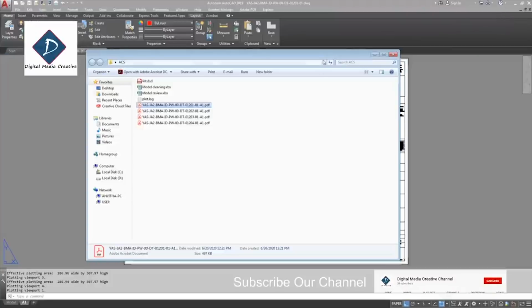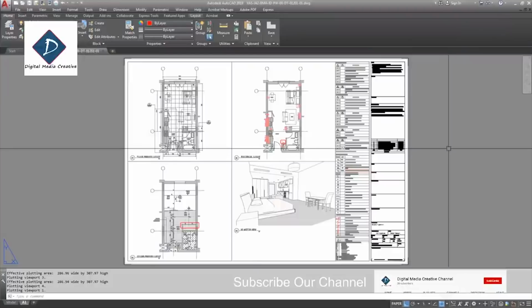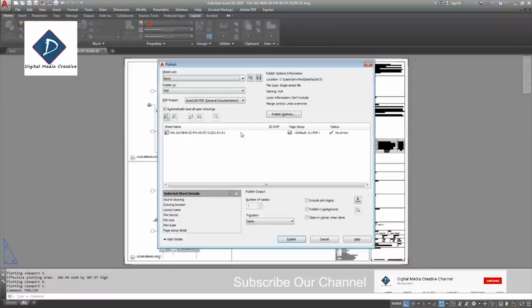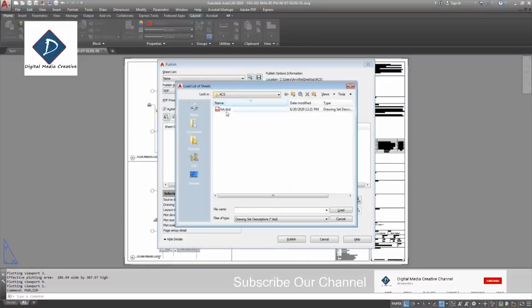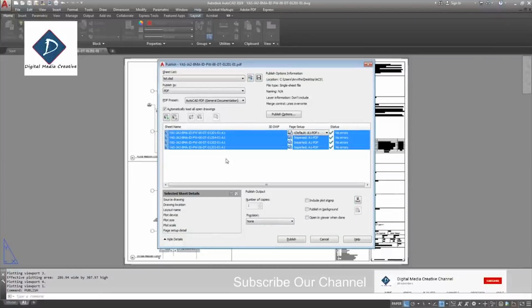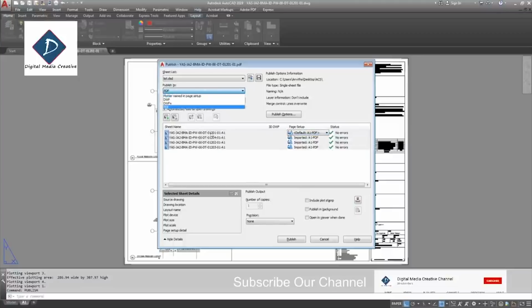So just make sure you have the setting. So okay, now we have the 4 drawings, I mean the list we saved, right? So okay, for example, I'm just publishing again and I'm just deleting. Okay, so I'm going to import the list. So I'm just clicking, so you can select the list. See, now if you want to make DWF, just change the setting, change here, that's all.